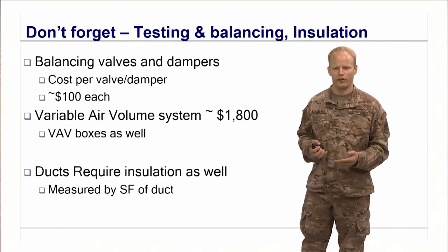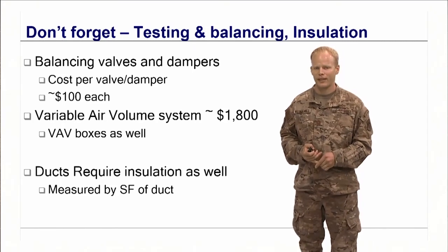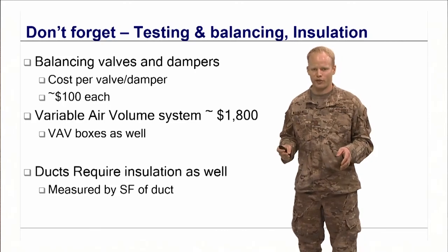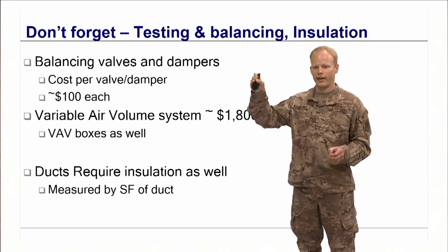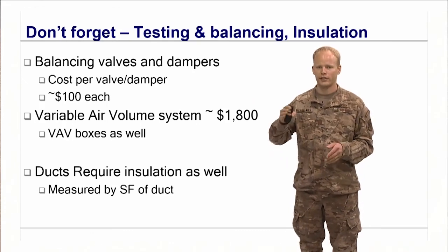But you also want to do it right. So the testing and balancing process ends up being very iterative. You test the system, you take measurements on one valve, you adjust one thing, and then you go check the other valves and you come back to that valve, and then you fiddle with it again until the whole system's in balance.